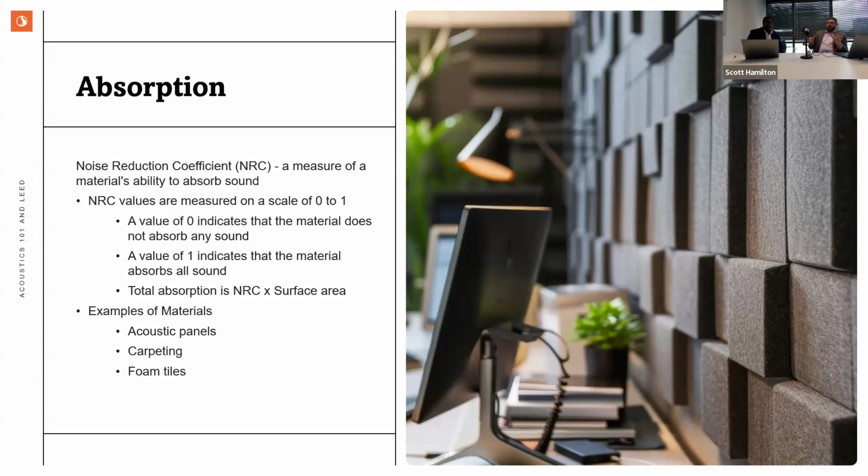I talked about acoustic absorption just a second ago. Acoustic absorption is literally, does the panel reflect sound or does it absorb it and dissipate it? We express that with an NRC rating. I hope this is the last acronym. No, it's not. Sorry, I thought this was going to be my last acronym. The NRC rating goes from 0 to 1, 0 being perfectly reflective, 1 being perfectly absorptive. You will see some products claim higher than a 1. That is scientifically impossible. They did their testing wrong.